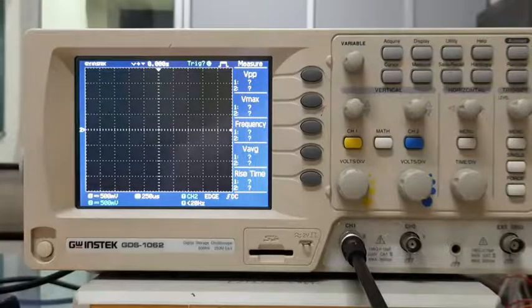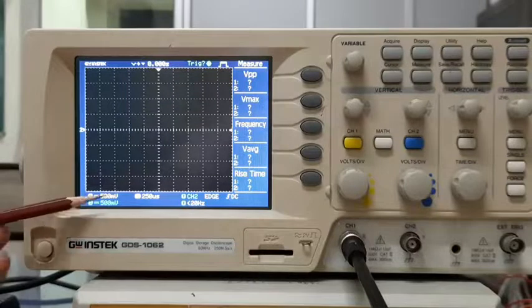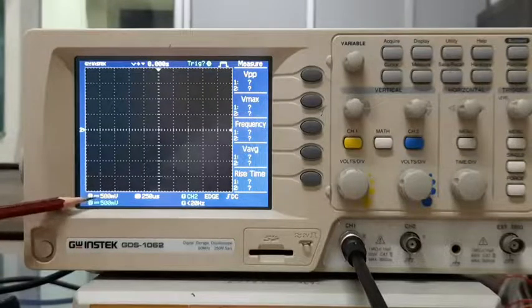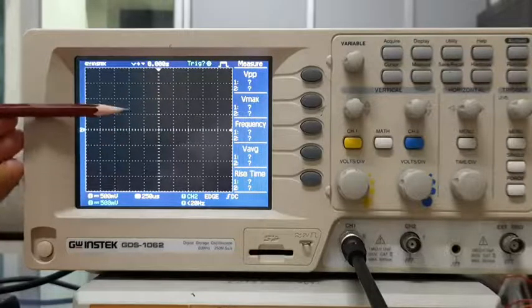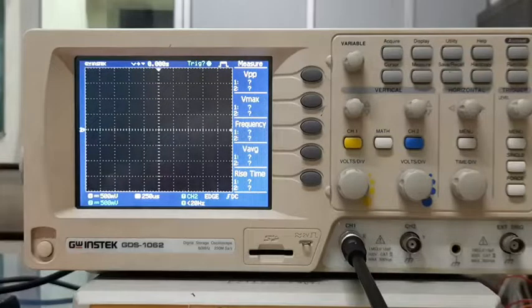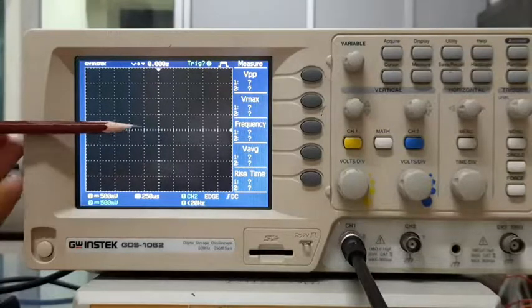So this sets a scale, and that scale is shown here, right? For example, here it's 500 millivolt. What that means is, each square box on the vertical scale corresponds to an amplitude value of 500 millivolt. So if this central crosshair